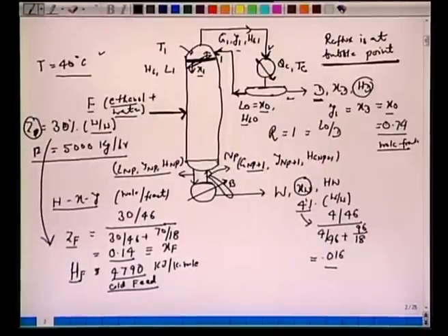Okay, so essentially we have marked the composition of the F feed, and we have marked whatever quantities are known here, XW, XD here, the top product. Notice Y1 is the same as XD, same as X0. We have put some specs for the vapor which leaves the top plate, the product which is withdrawn here, the feed here, the liquid which trickles from the bottom plate NP, the total number of plates, and the vapor which leaves the boiler and arrives at plate NP. The question asked in this problem is, given the HXY diagram and the XY diagram, two equilibrium specifications.